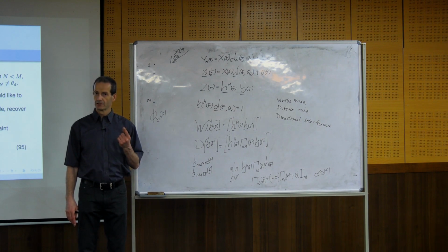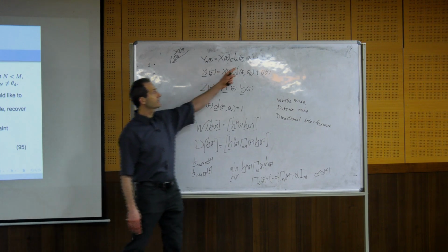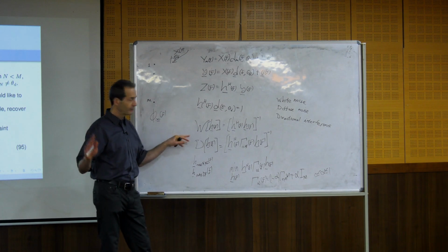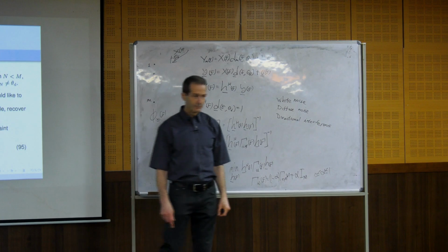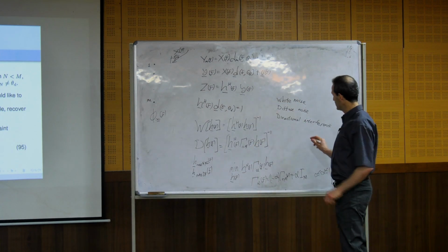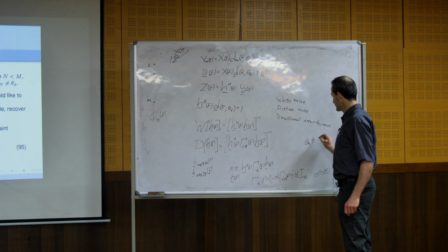Okay? So if we go to a real environment, and instead of theta d, suppose that I designed the beamformer for a specific theta d. And instead of theta d, in an actual environment, it will be theta 0, which is different than theta d. It will be a different angle.